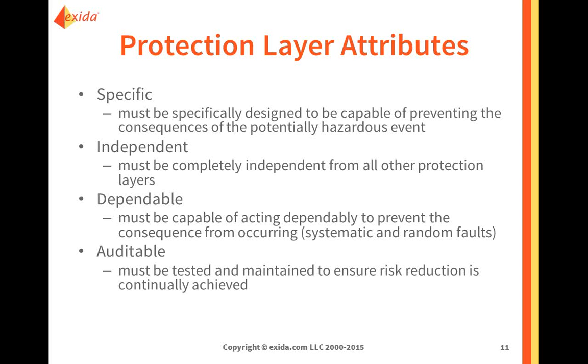One is the valve and one is the operator taking action. So instead of saying, hey, I have two layers, what you need to say is, hey, I got only one layer, but the final element is a little bit better than a single final element would be. You've got diverse final elements.